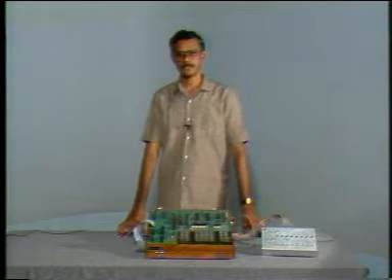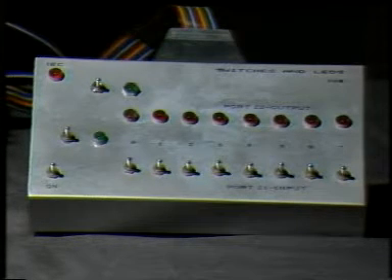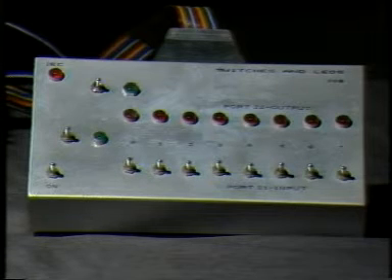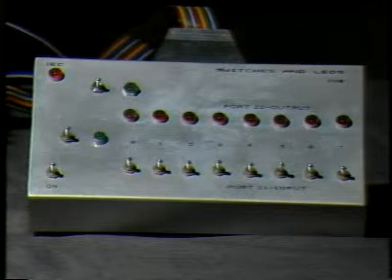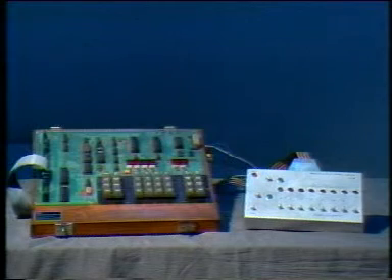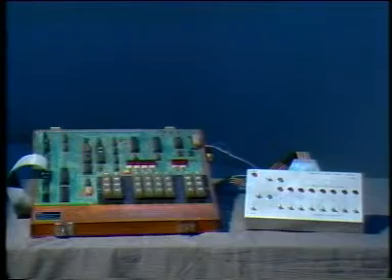Having learned the details of 8255, let us view a demonstration in which external devices are connected to 8255. The external devices connected are LEDs and switches. The 8 switches are connected to port A and the 8 red LEDs are connected to port B. The port A is operated in input mode and the port B is operated in output mode. The device is operated under mode 0. A program is executed which will switch on the LEDs one by one in sequence.